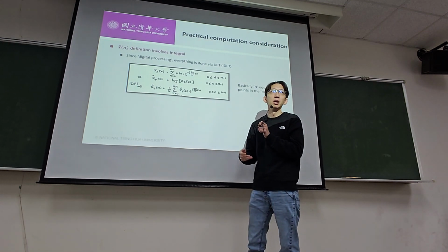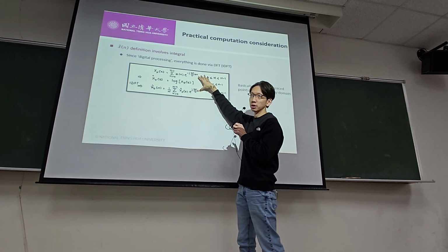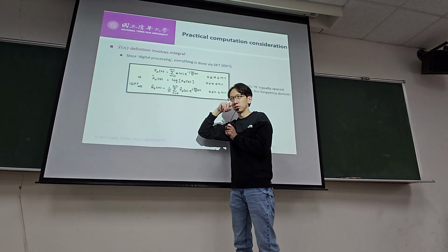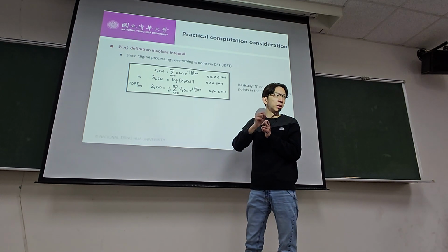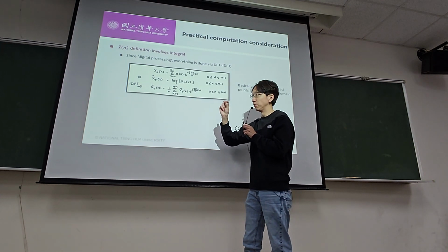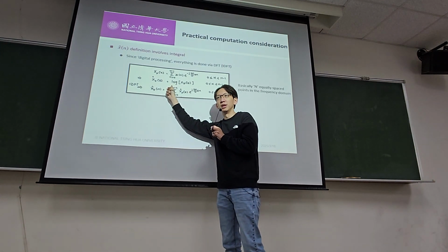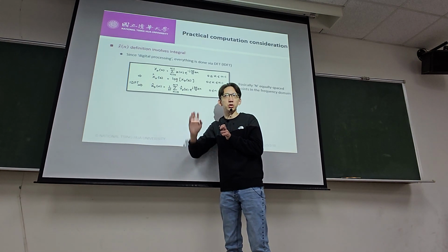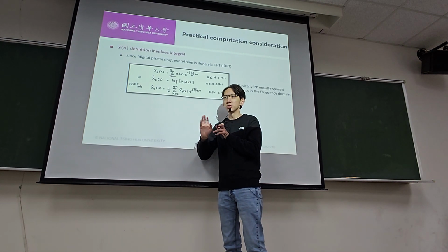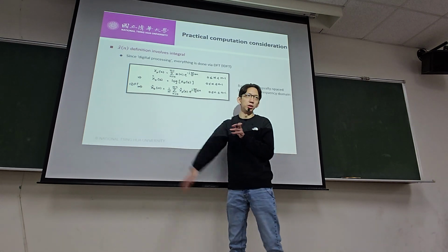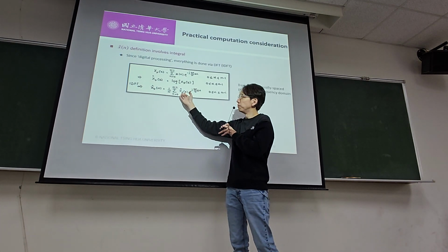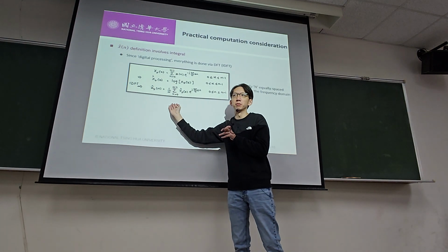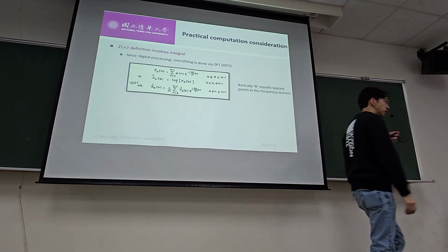In the cepstral domain, it follows exactly the same logic. Now you just stick a log into the thing. So cepstral domain transformation is nothing but taking a log in between, and that's it. Everything else is the same as though you're trying to do a Fourier transform, any transform and backwards, back to the original domain. But because of the log, you don't call it time anymore; you call it cepstrum. That's the only thing that's different.